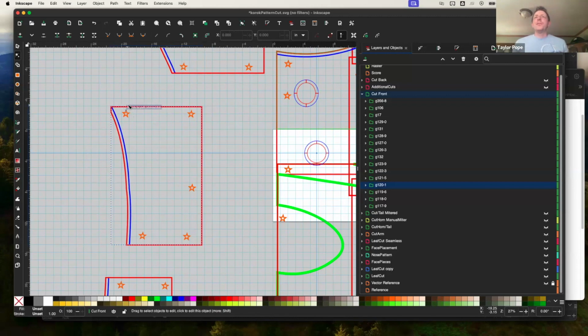The firmware that translates into laser instructions can take these paths, which, instead of being composed of pixels at a given area, are a mathematical formula for calculating the path to draw. The laser can then follow that same path, and instead of drawing pixels on a screen along that path, it can move the gantry or galvo to trace the point of the laser along that path to cut or engrave the underlying image.